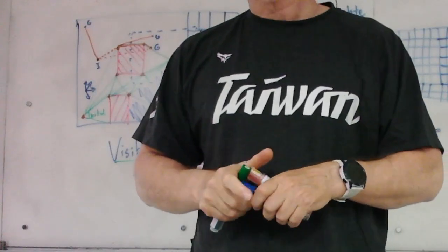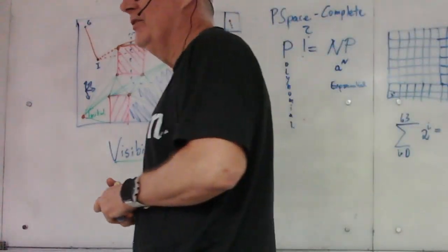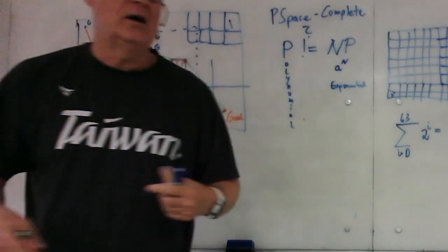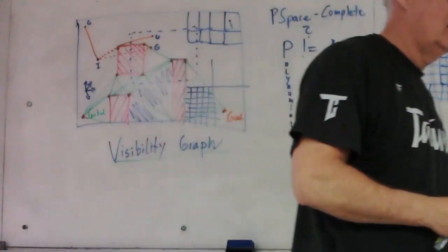As close as possible as it can get to this edge. And if you've ever tried that, that's a really difficult problem for your robot unless you actually have an ultrasound or laser range finder going out to the side that can measure the distance to the wall. Wall following is not for the faint of heart with your robot. So this is a very aggressive policy that in practice is doomed to failure because of the noise in our sensors and the noise in our actuators.